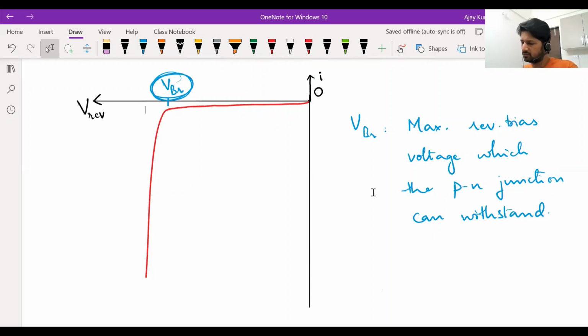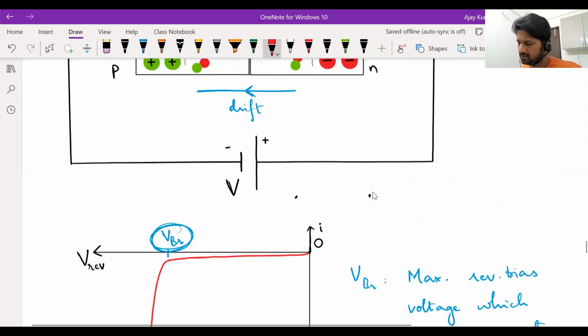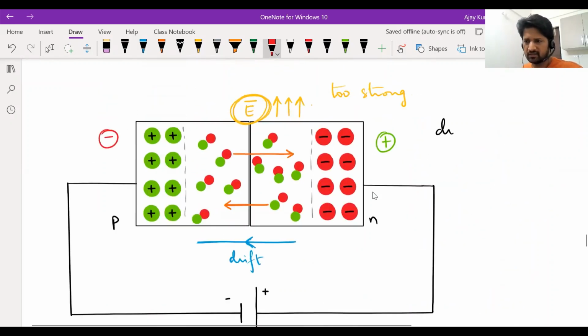Once the voltage exceeds the breakdown voltage, there is a sudden increase in the reverse bias current. Now, regular PN junction diodes cannot withstand such high currents. Cannot withstand means what? Due to the heat generated, they'll usually get burnt, damaged. But a Zener diode is made of materials which can withstand such large currents, or such sudden changes in currents. I'm not saying a Zener diode can withstand any amount of current, but they can withstand significantly larger currents compared to usual diodes.